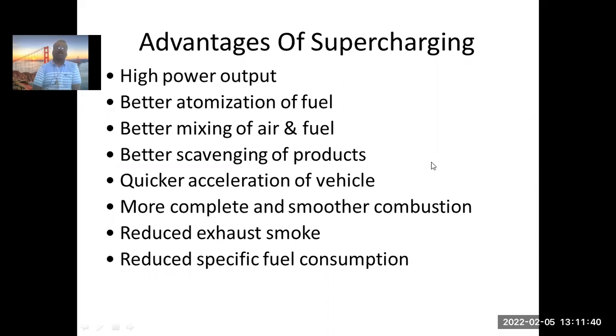Yes, I will define the scavenging first. Scavenging is the process of flushing out of the burnt gases from the cylinder. That particular process is what we call scavenging. Now here we are saying due to supercharging the scavenging is going to be better. How? Anybody? Get more to burn the fuel. Okay, anything else? Anybody else?